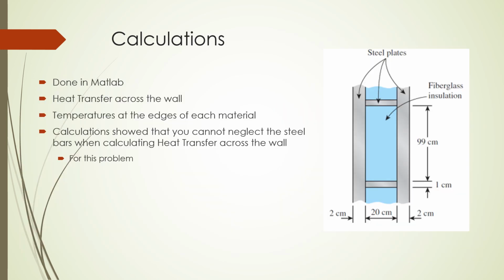So for the calculations, they were all done in MATLAB. We found the heat transfer across the wall, temperatures at the edges of each material, and then there are calculations that showed you cannot neglect the steel bars when calculating heat transfer across the wall.